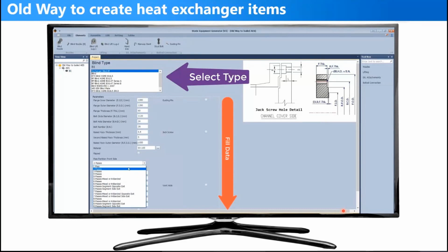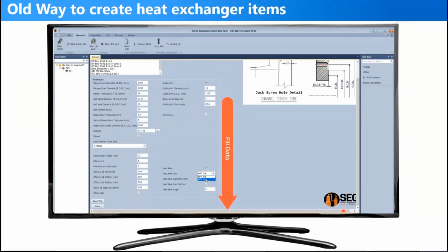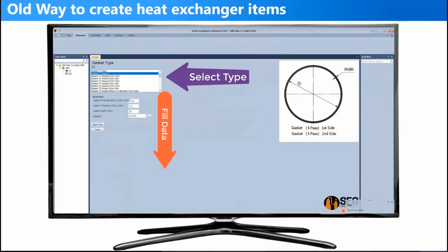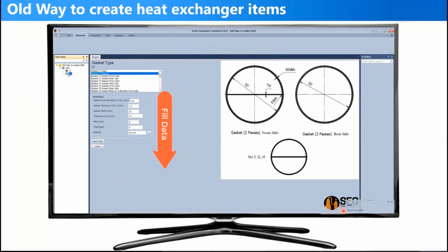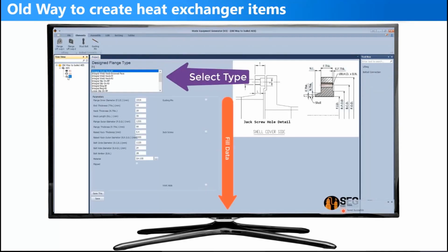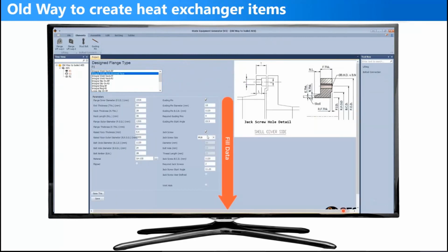So as you can figure, we add a blind nozzle. After that, we add a gasket and flange. To generate a channel, we will add the items separately. So the channel includes blind, gasket, another flange, shell, flange. Okay, so we will generate those items